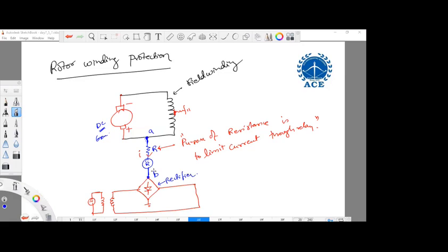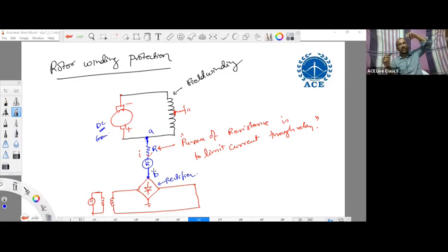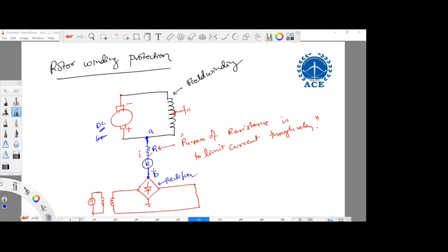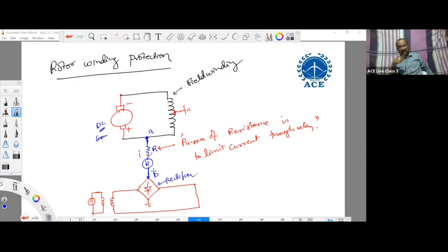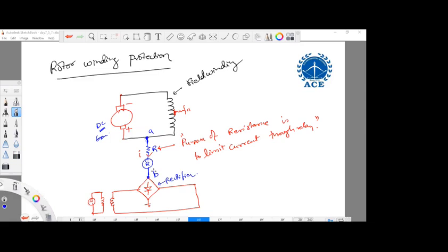And that current should be circulated only during that harmonic point. So that delta circuit will allow the currents during harmonic induced voltages. So tertiary is nothing but a harmonic circulating winding. Actually, it will allow the circulating currents for the harmonic induced voltage. That's why we use that.